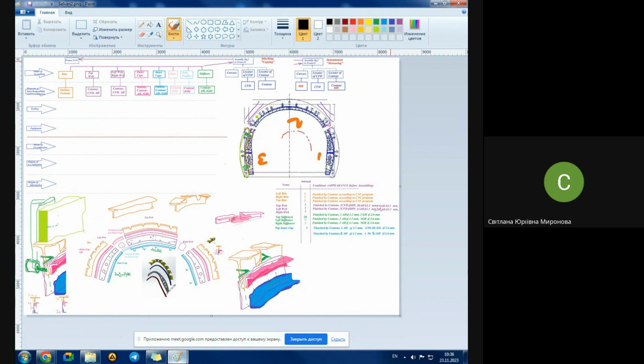When you are thinking about the sequence of assembling, you are also thinking about the basis assembly method, what is first and how you locate it, either to the base of the jig or to the base of another part, which is already preliminarily located in a jig or on a workbench or whatsoever. The first thing we did after the sequence of assembling is the locating chart. We already understand all the methods of assembling for each part, all the bases.